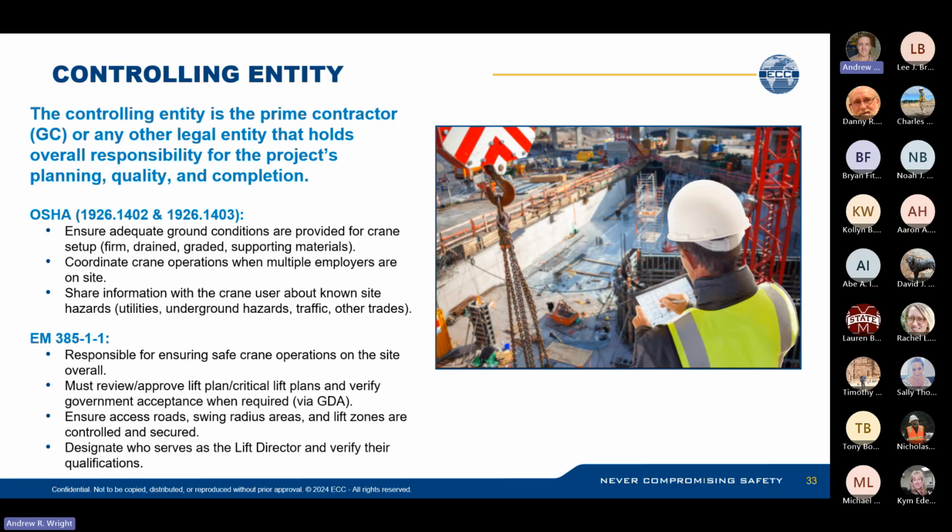That's why it's really important for the SSHOs to get out there and really do a thorough inspection of the grounds. Sometimes you'll set up a crane and there'll be storm drains, or there could be tanks stored underground. You could always reference as-built or reference drawings to see if there's any potential for anything underground that you don't see.